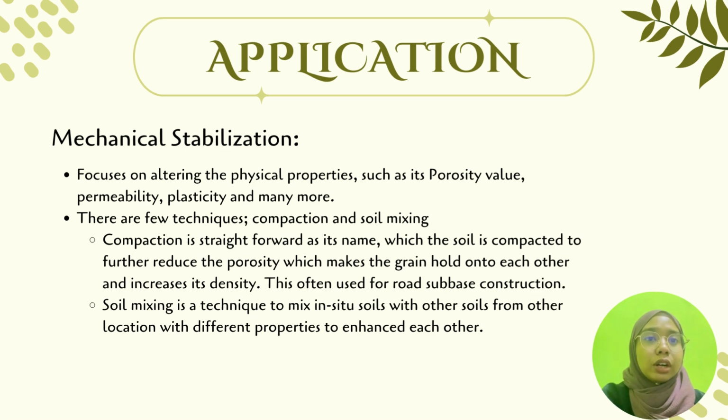There are two types of machinery that they will use to compact the soil, which are the big roller machinery and the plate compactor. They will use either one, depending on the size of the perimeter of the site. If the site is bigger, they will use the big roller machinery. But if it is a small area, they will use a plate compactor.